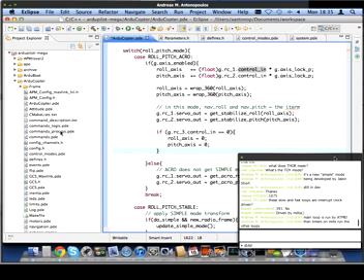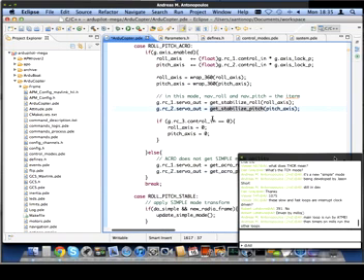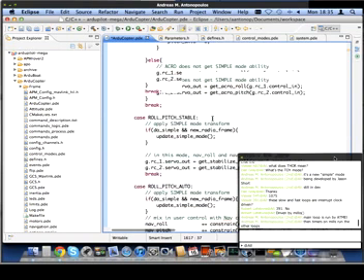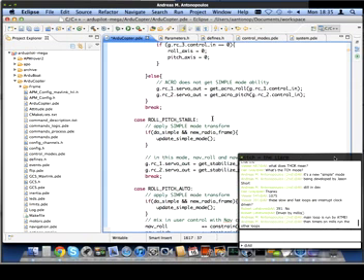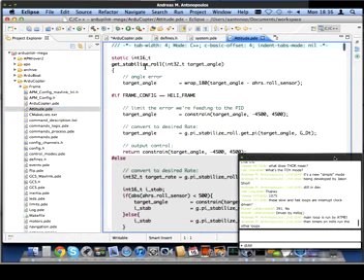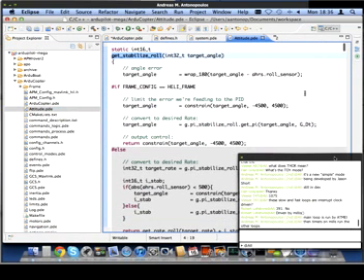We're then passing that into functions which are held inside of the attitude.pde, like get_stabilize_roll. Those functions will return to us an output, like a desired roll output, which we put into servo out. And then later on, you'll see that we'll pass those servo outs into the motors code.